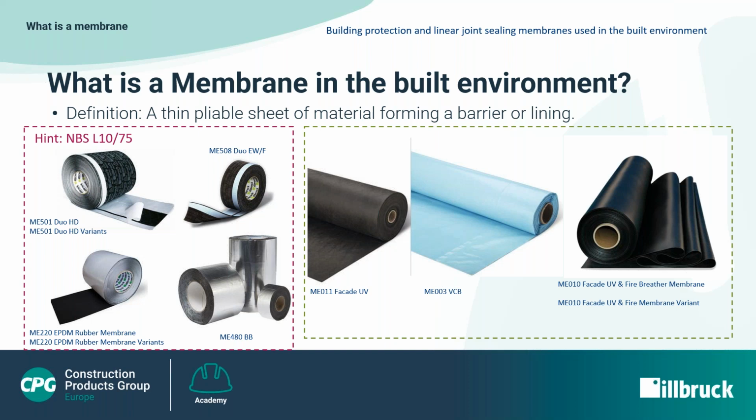Membranes are used in this context to provide a barrier or to prevent something getting in or out, but are often required to be diffusible, allowing vapor or other gases to pass but not liquids. Conversely, some membranes are used to prevent the transfer or diffusion of gases. It very much depends on the application involved. Membranes do not and cannot provide a barrier or insulation against fire, but where relevant buildings are concerned, membranes must achieve a minimum reaction to fire.